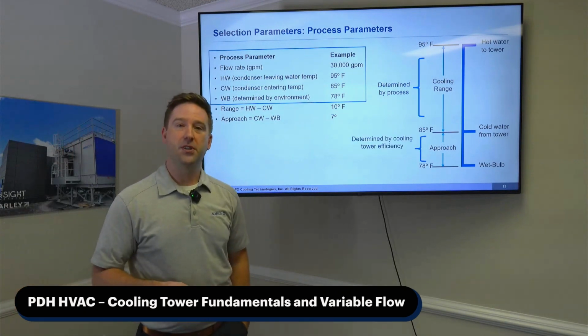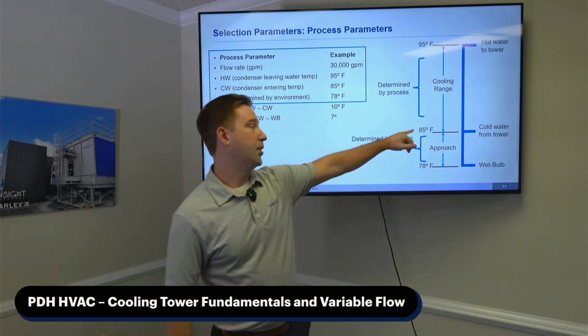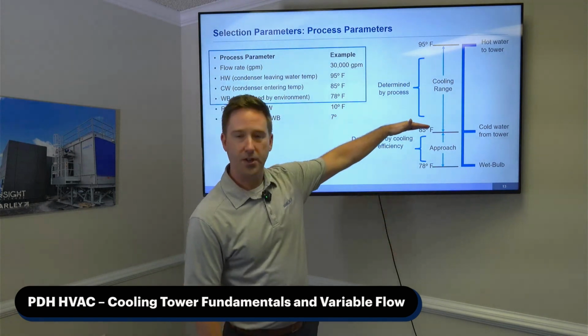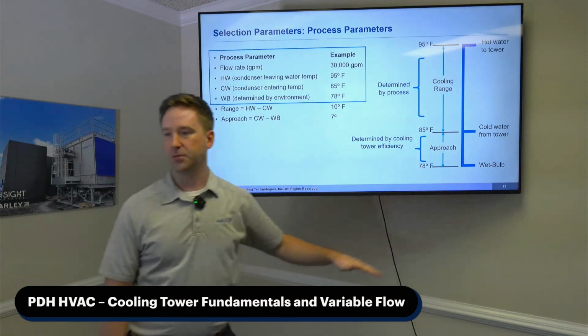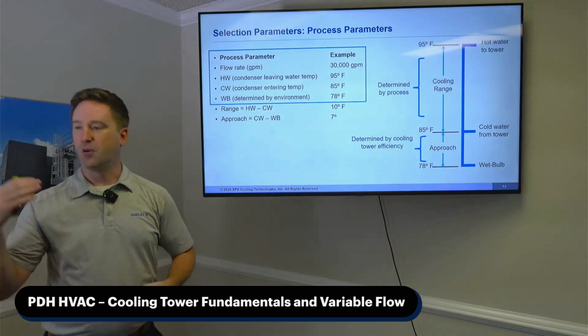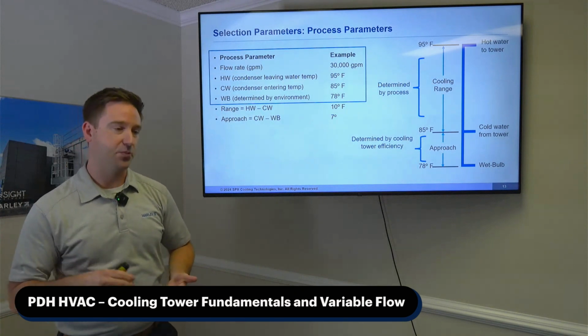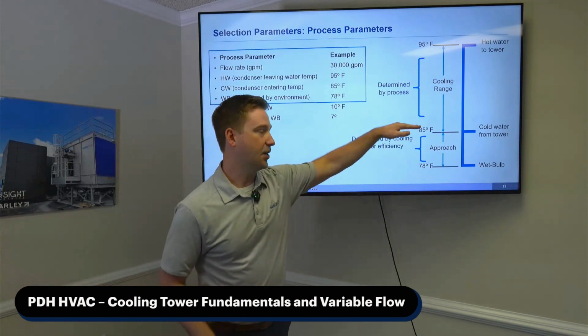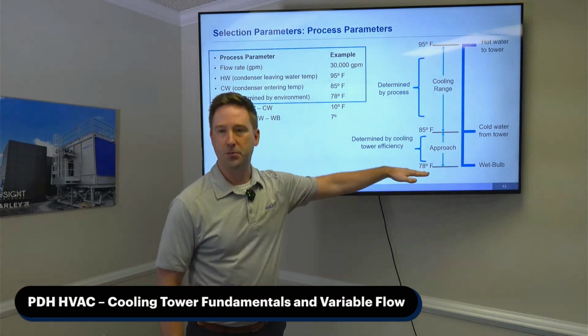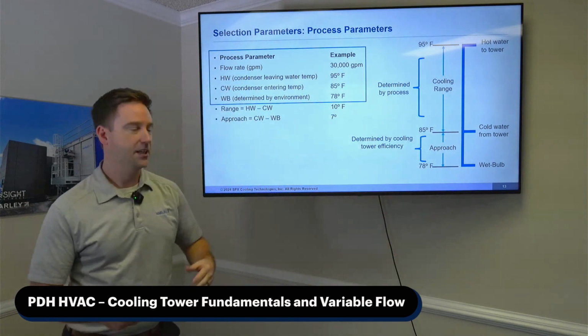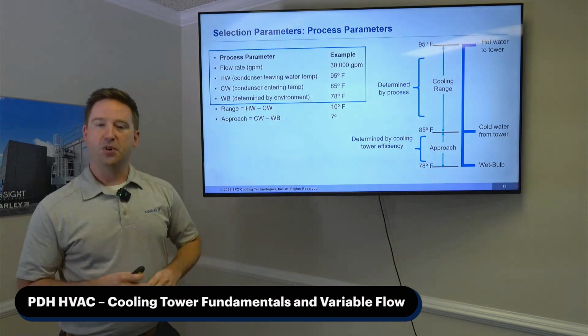Another term that we're going to talk about here is our approach. And that's the difference between your cold water temperature and your wet bulb temperature. Kind of going back to our beer in the refrigerator example, you won't be able to get colder water than your wet bulb temperature. So, things to keep in mind.